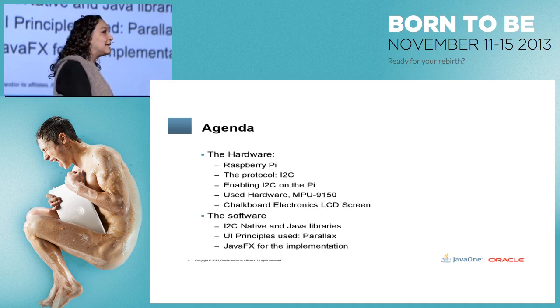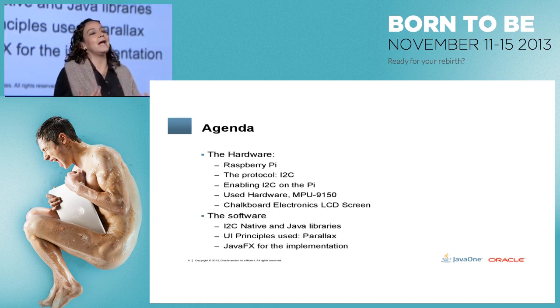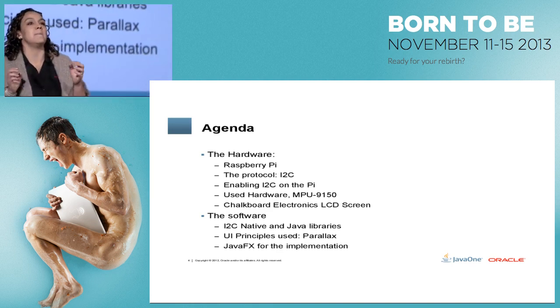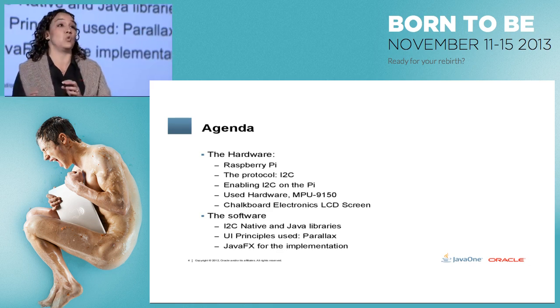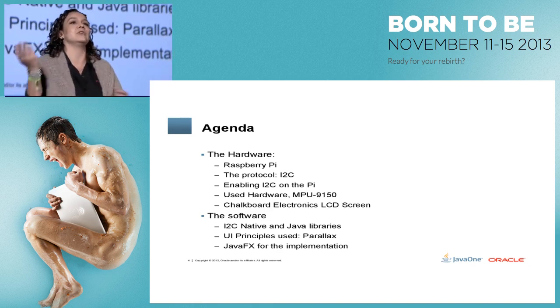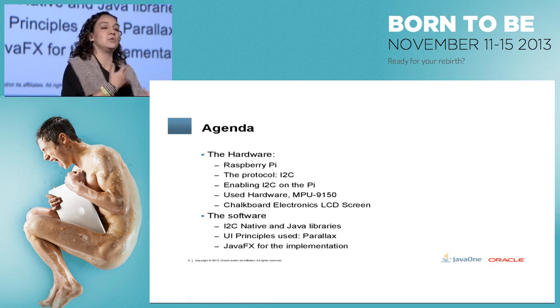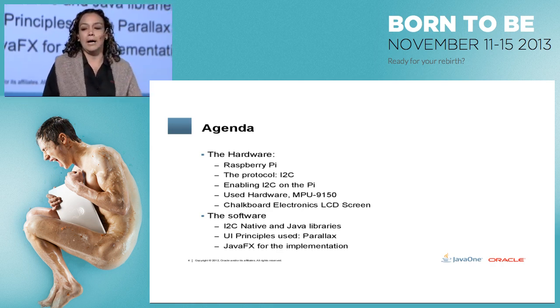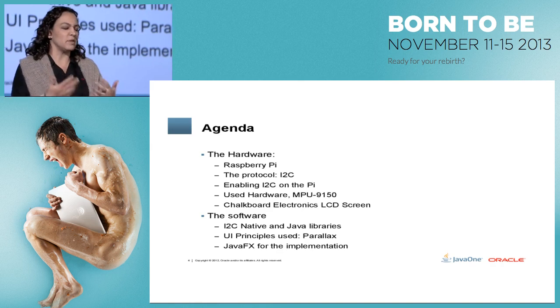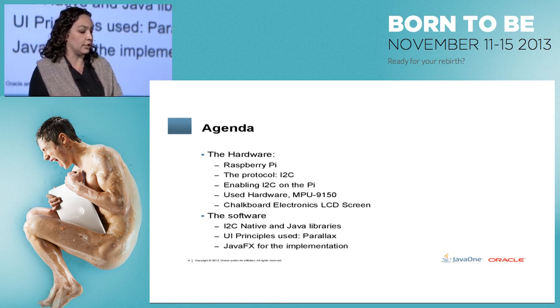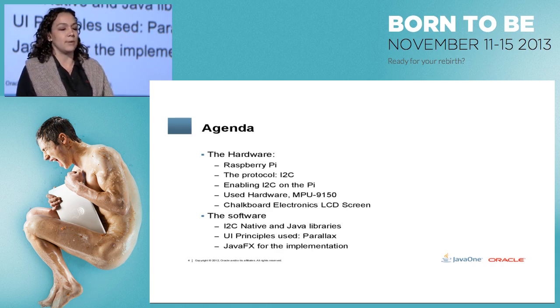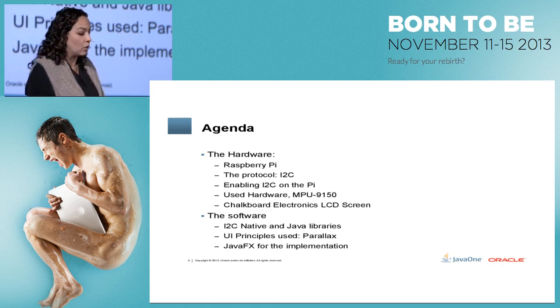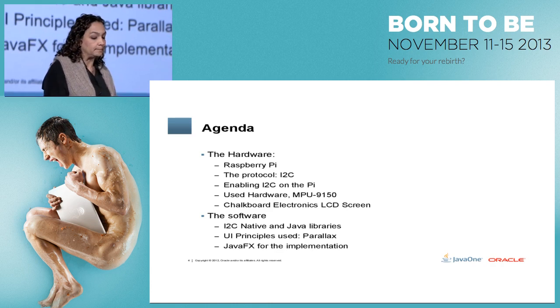And digging into what was going on, I found that the Raspberry Pi has a blacklist. So if you are in the blacklist, you're not going to work. So you have to take those out from the blacklist to be able to enable your device, and sort of things that you have to actually do before you can use I2C on the Raspberry Pi. So it wasn't really straightforward, and that's why I want to cover it.